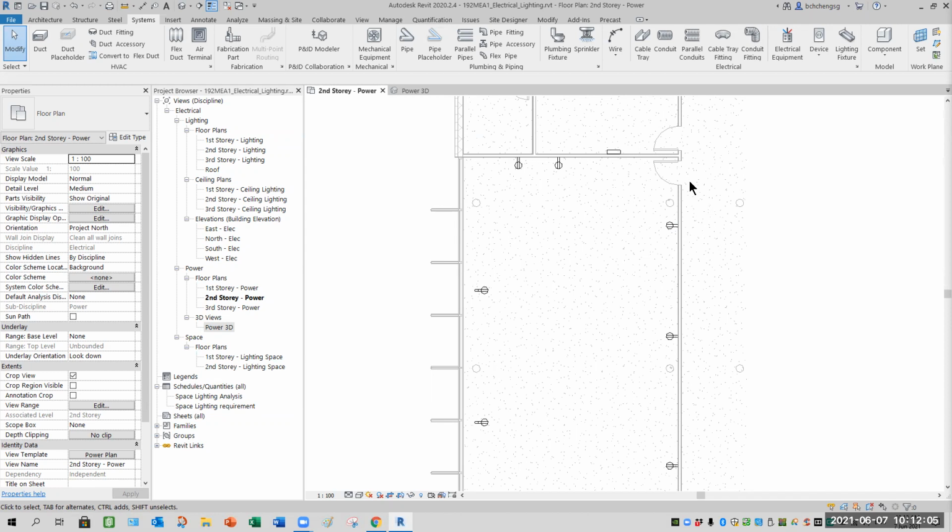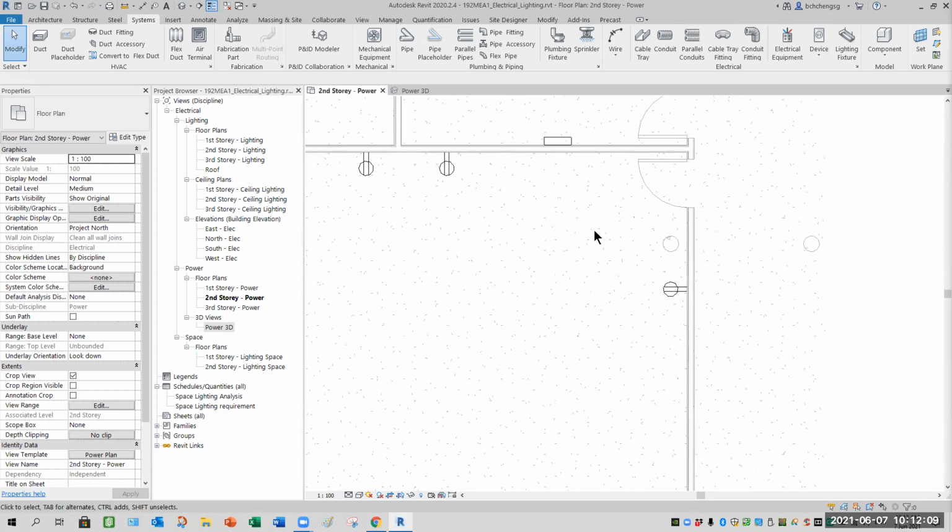So in your plan here, how are we going to add the dimension? Ready? To ensure that your view here is not in fine detail level, it should be set as coarse, so that it is easier for you to do dimension capture.